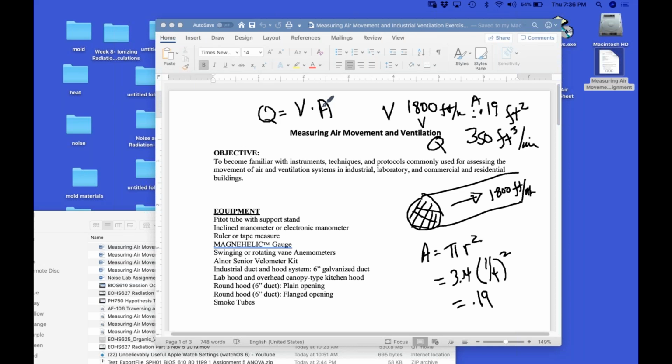If you hold this against the front of the hood, that's a hood. What's the reading right now? 2.99 feet per minute. Okay, right now move it back 6 inches. Keep going. There you go. Now you're about 6 inches. What's your reading now? 617 feet per minute. 313 feet per minute. 168 feet per minute. At 6 inches, it's reading roughly that.